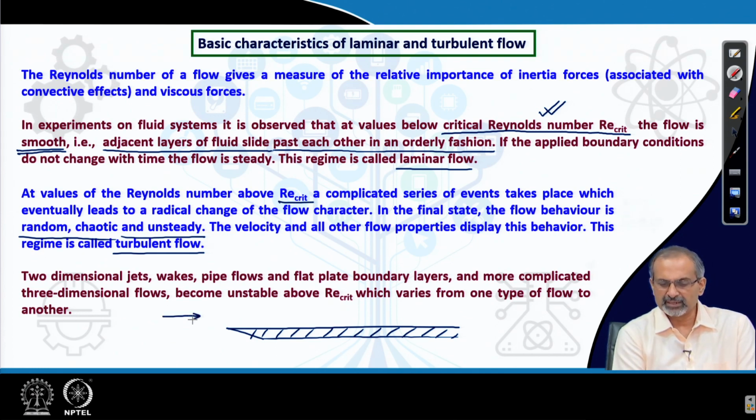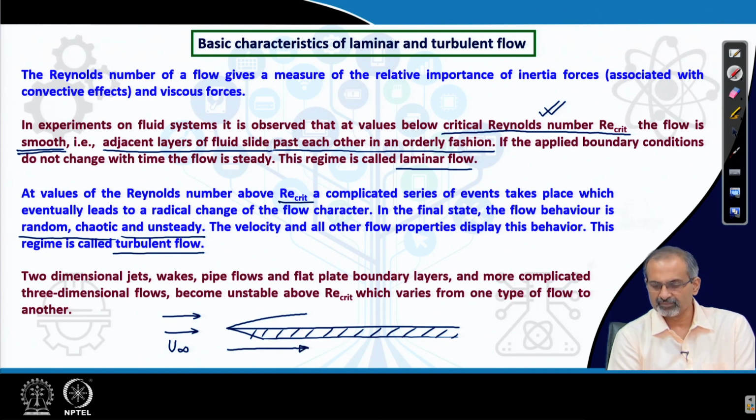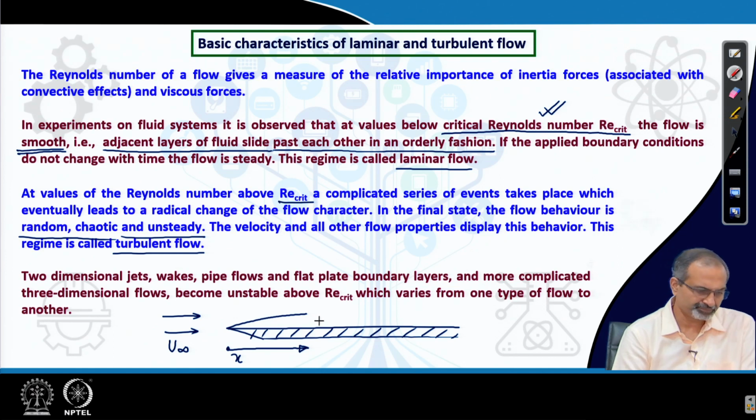So, if we continue with the incompressible assumption for now, that means for comparatively lower velocities, we start off with the same laminar boundary layer, but if we follow it for a considerable length along the streamwise direction, then what we will notice is that gradually some flow instabilities start growing within this boundary layer, and they also get amplified as we move further downstream. As they get amplified, more instabilities develop and gradually it turns into a very different flow regime, which is the turbulent regime.